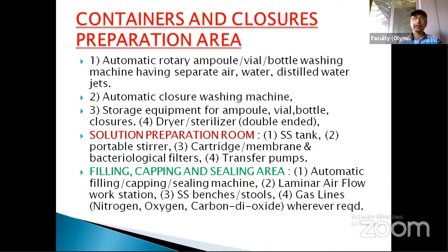Filling, capping, sealing area. Here an automatic filling, capping, and sealing machine is required. Laminar airflow benches are required, workstations under which you have to fill the injections. Though you are controlling the air of the entire manufacturing unit, whenever you are exposing your injectable liquids, that place is also centrally air conditioned through a very high grade of air. Clean room facilities of class 100 are provided there. But then also, another check: when you are filling, it will be done under a laminar airflow workstation.